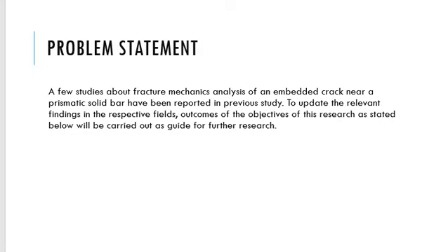In practice, however, engineering components or structures are often subject to combined loading, which in turn causes mixed mode fracture too: Mode 1, 2, and 3. In these cases, calculation of stress intensity factor becomes more complex. Evaluation of stress intensity factor under combined load has been an interesting research topic worldwide. Some methodologies and techniques have been proposed by researchers.